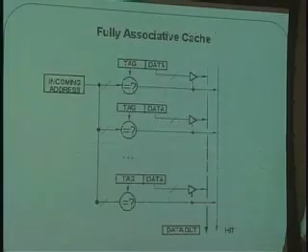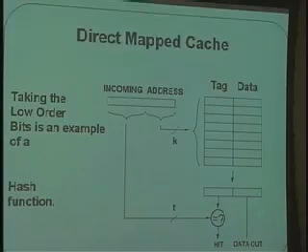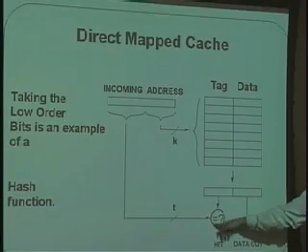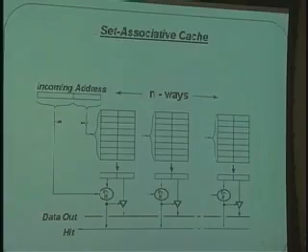And so the direct map one is less expensive, more straightforward, and easy to make because there's only one of these things, but on the other hand, it's not as high performance as the other one. It can suffer from these collisions. Is the hash function just stripping off the higher order bits? In the case of caches, that's all that it is. Now, hash functions can be fancier than that, but this hash function is just trying to strip off the lower order bits.